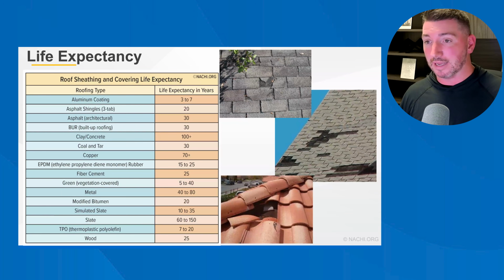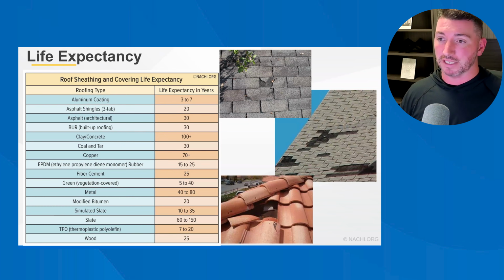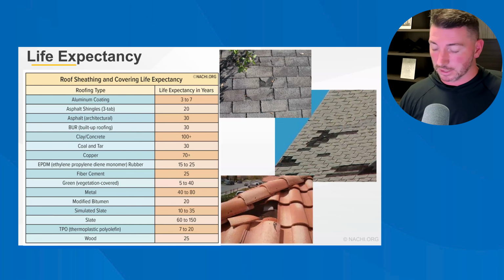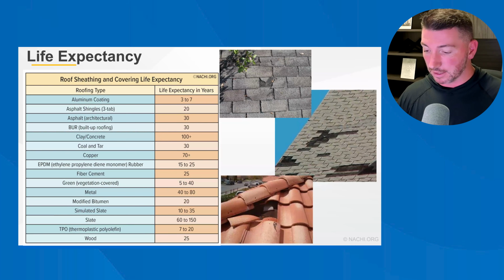Now, moss, lichen, those things, especially lichen, has a very basic chemical compound, in terms of basic versus acidic. And it does eat away at the shingle itself. And when that lichen dies, it will create some damage to the roof. So, not all organic growth is good for the roof, but algae is really not a huge problem other than it's very unsightly. And if you're a man and you're married, get the soft wash if your wife wants to soft wash. Just wash the algae off and plan on replacing your roof a couple years earlier than you would have.